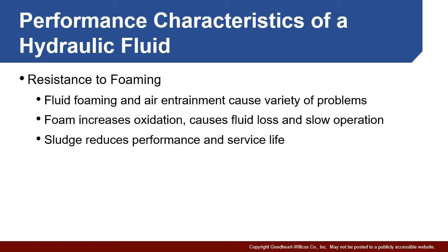It's thick and it's significant problems in terms of the performance of the equipment, providing a lot of issues with friction and potentially wear. And of course, it's going to reduce the service life of the oil and potentially the service life of your equipment. So I want to make sure that foaming is prevented as much as possible in our hydraulic fluid.